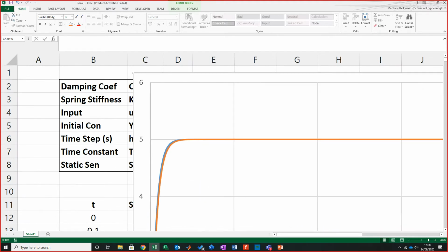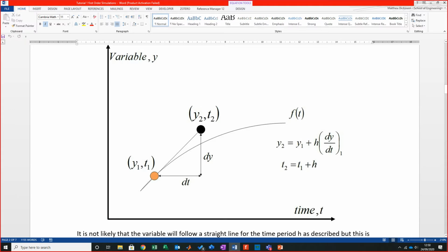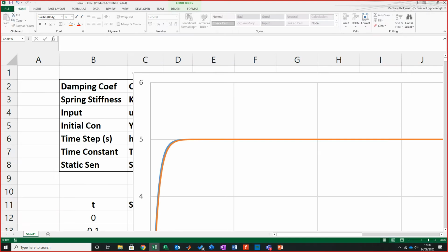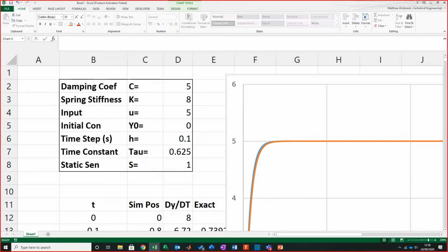Now you see the arc, it's more blatantly obvious. The reason is that my iterations between each recording have been doubled, so there are fewer points of velocity being predicted to give us that result. What we end up with is a far stiffer response.